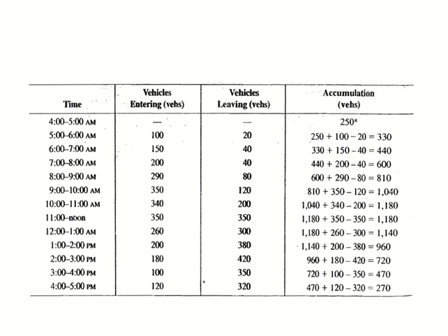So you can see that it starts between 4 and 5 a.m. and they have taken an initial count of how many vehicles are accumulated inside the area. These are the vehicles which are basically parked on the street side, so maybe some of them are on the streets moving. But the reason for doing this count so early is that we don't have any vehicles entering and leaving, so we know this count is stable.